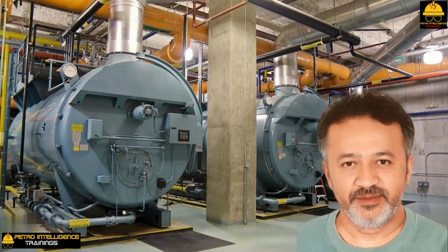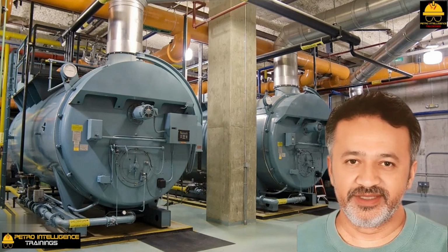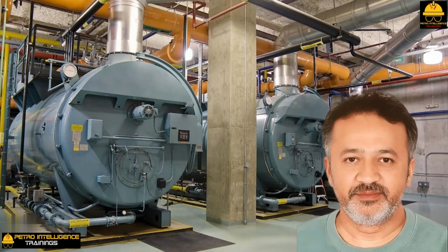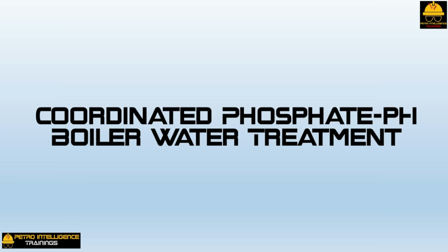Although skimmers and diatomaceous earth precoat filters can operate at higher temperatures, that is 175 degrees F, the temperature limit is usually based on the temperature at which silica dissolves. Incidentally, the typical optimum pH of water in a boiler is close to 9 to retard boiler tube corrosion, shown in picture.